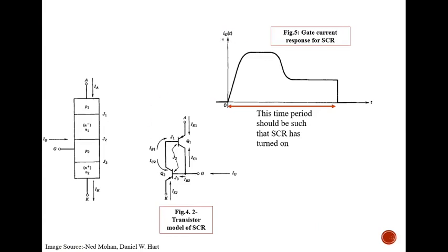If you are applying the gate current, how much time is needed to apply it? Because there is no need to turn on or turn off the thyristor with it. The only gate current requirement is at the turn on procedure.